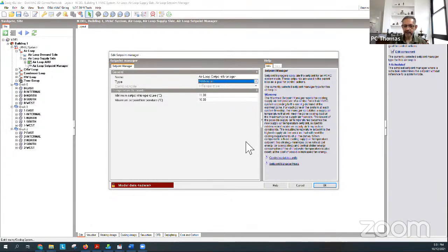Then it will work out the supply air temperature to just meet that load, and it will supply air only at just that temperature. Okay, so all the other zones may require less cooling than the supply air temperature that's set there. That's when you have a VAV box, and the variable air volume box will then slowly close. For those other zones, it will control the volume. Okay, so we're getting pretty heavy into the mechanism for a VAV system.